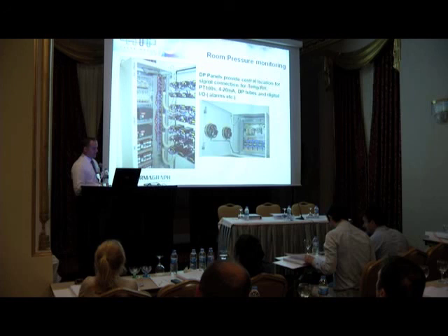So the optional batch reporting allows trend, alarm, and audit log reports to be automatically generated. And this is by a batch mentality rather than a time-based method. You select which counters and environmental sensors will be included in the report, because it might not cover the whole system. Select which reports are required: you want a trend, alarm, or historical data. Then you enter the start of the batch, and then you give it a batch code. Then you can save that into a PDF format and record it however you want.